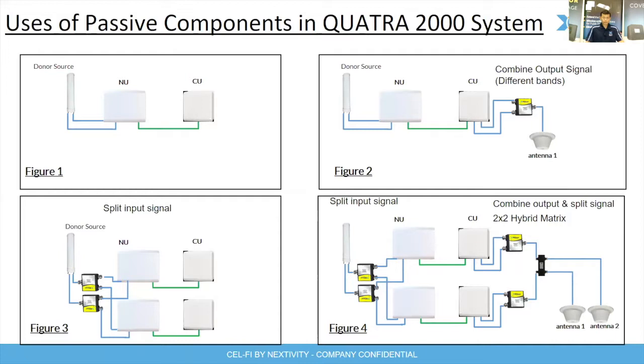Okay, could I split and have 2 MIMO antennas using 2 splitters? Yes, you can, in actual fact. There is also another way, but it's not right, it's not wrong, but nowadays we try to reduce the number of antenna that is visible because customer perception is they do not want to see too many antennas, right? If we can combine the one antenna or the least amount of antenna visible, the less is the best nowadays. Okay, but if we needed 2 for coverage, for instance, we could do that. Yes, you can do that.